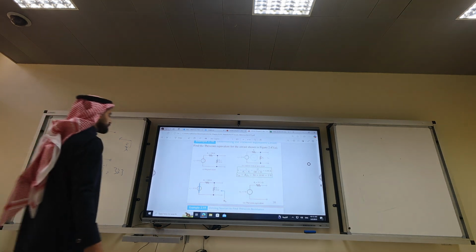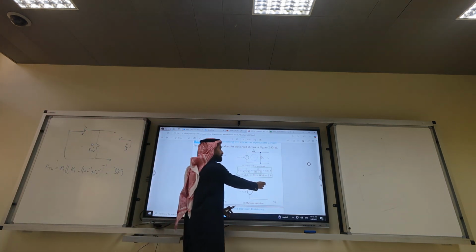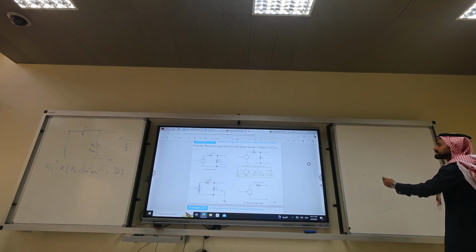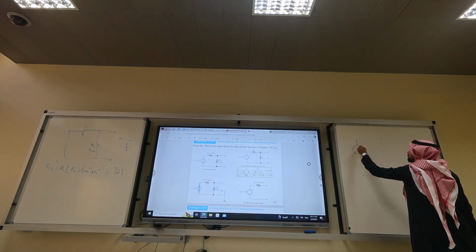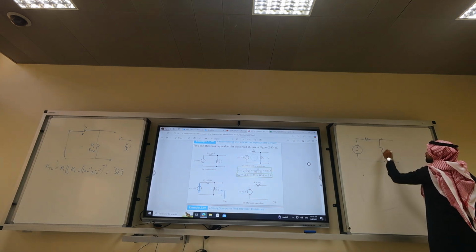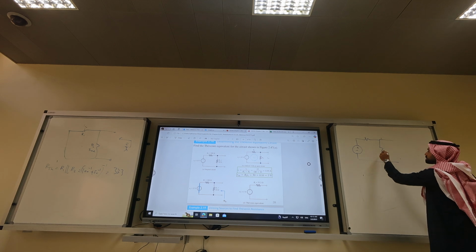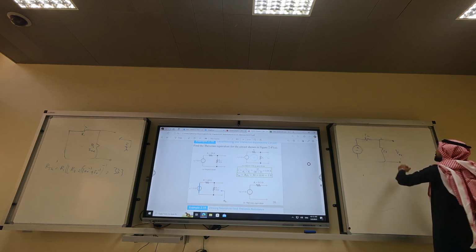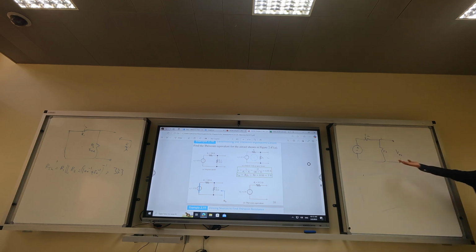Okay. So R Thevenin is 33.3. How to find V Thevenin? Well, you go back to the original circuit and you try to find V open circuit. R1, R2, original circuit: 50 and 100. Is it worth doing node voltage analysis? Is it worth doing mesh analysis?